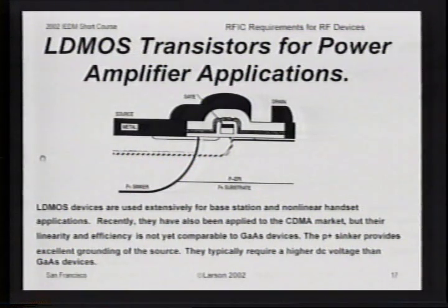Now, there's one class of MOSFETs which is different from traditional MOS devices, which is very commonly used in the RF business, but it's rather quiet, and it's a very unique custom kind of device, and that's what's known as an LDMOS device. LDMOS devices are probably used in 95% of all base stations worldwide because they're able to produce extremely high powers in a very, very low cost manner. So LDMOS devices are RF devices that have a real unique use within the RF field, but they're very, very different from traditional CMOS devices.